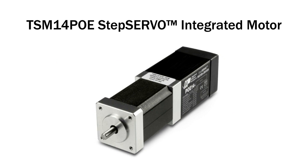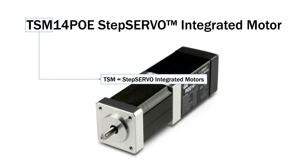So it's a little bit of a mouthful. I'm going to break down some of what's in here. TSM refers to an entire family of step servo integrated motors that we offer. If you are new to the term step servo, it was our trade name for closed loop steppers. So we take a traditional step motor, we put an encoder on it, and we run it with servo controlled firmware so that we can servo the current, the velocity, and the position. So basically, we run a step motor like a servo motor.